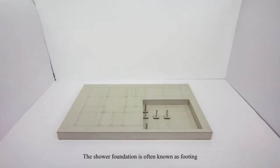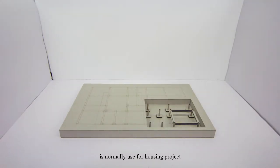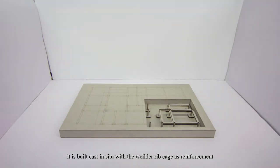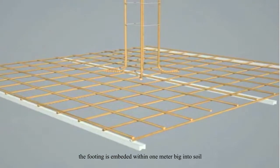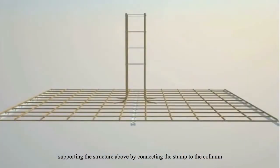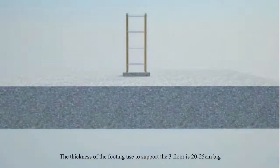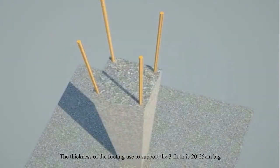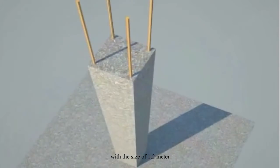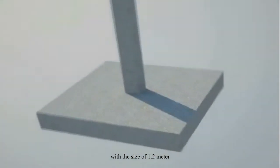The shallow foundation is often known as footings. It's normally used for housing projects. It is built cast in situ with the welded rib cage as reinforcement. The footing is embedded within 1 meter deep in the soil, supporting the structure above by connecting the stump to the column. The thickness of the footing used to support the 3 floors building is 20 to 25 cm thick with the size of 1.2 meter.